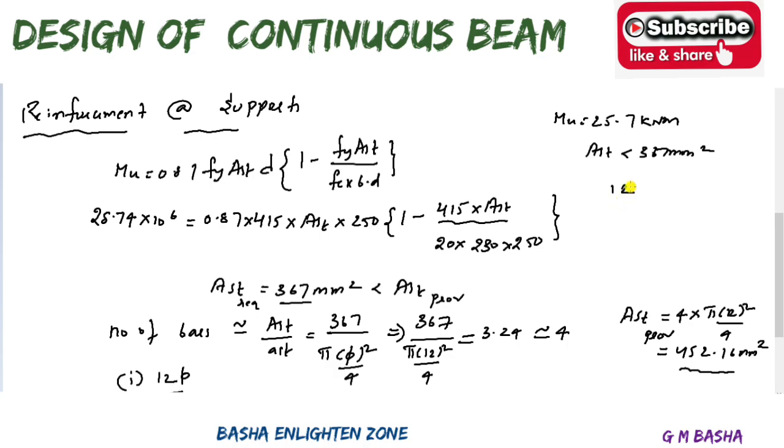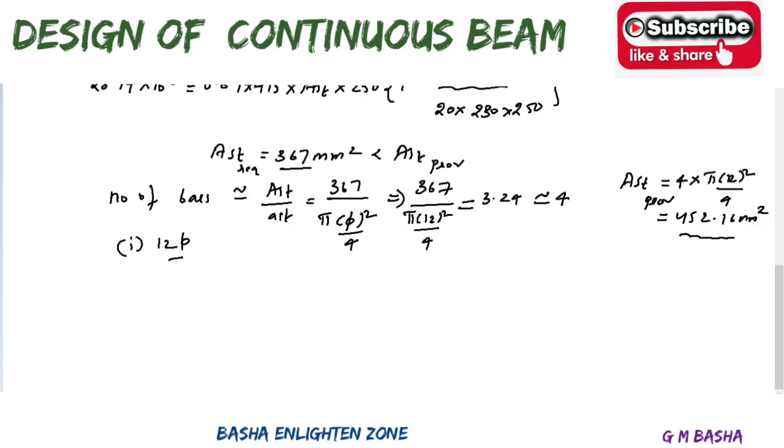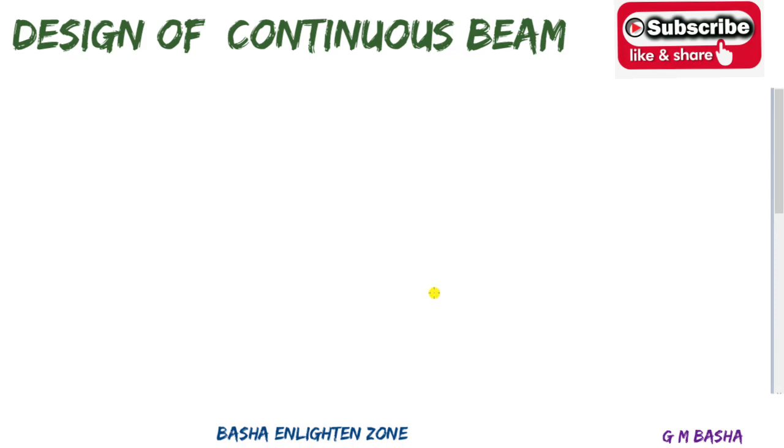Therefore, what I am telling is, check the higher moment at the supports and you can provide the same reinforcement to the lesser moment also. Don't check each and every moment every time. If you want economical calculations, you can check with this particular value and provide a suitable value, no problem. Okay, then I will go to the next one, which is reinforcement at the middle spans. So, reinforcement at the mid spans.